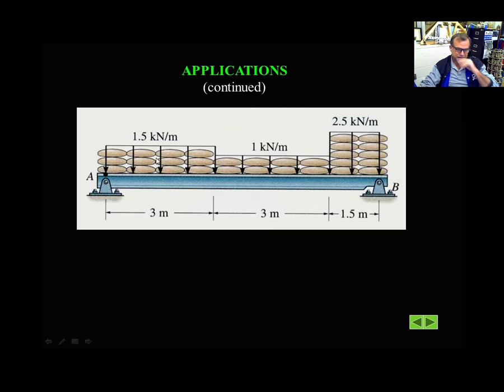That makes sense. That's something logical. That's something that you have done before by inspection. What is the total load here? 3 times 1. What is the total load here? The first 1 meter is 2.5, and the second half meter then has to be half of that.